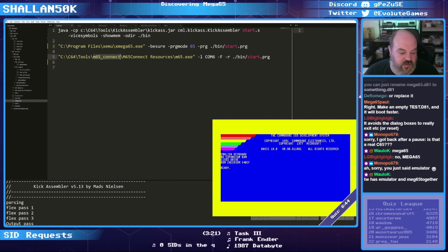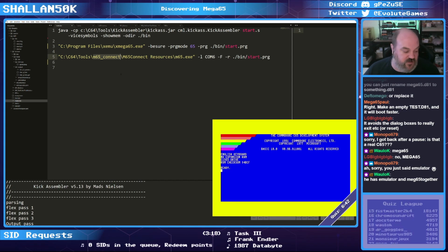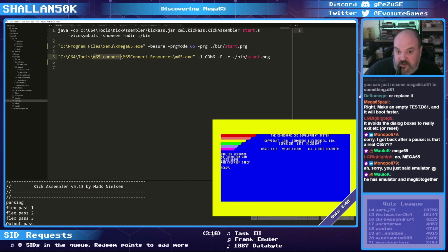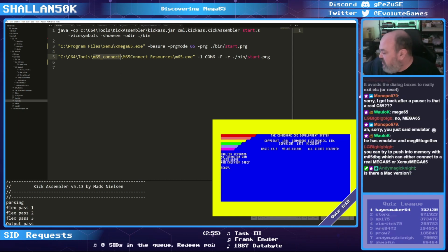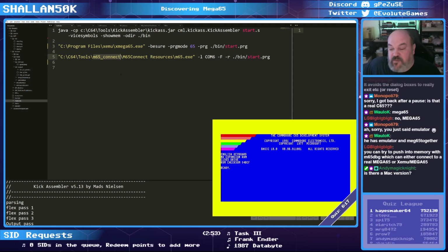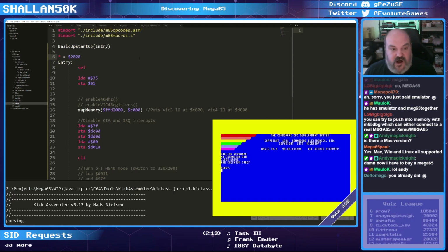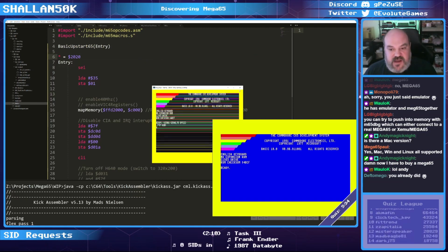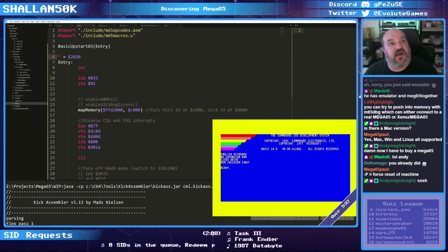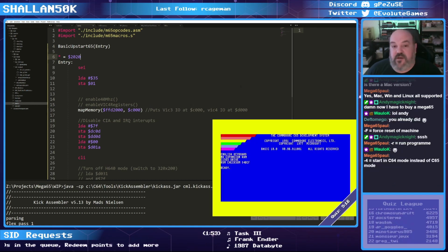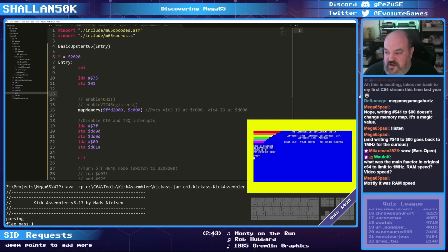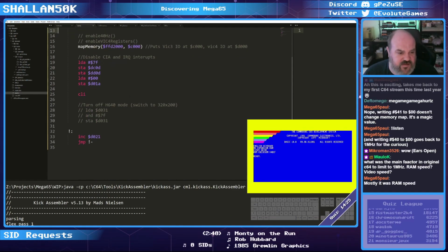Now that is available through the Mega 65 GitHub. What it allows you to do is, through the command line, launch PRGs over the JTAG connector through USB. If I try and load a file, it will do the build and launch the emulator. Then as soon as I quit the emulator, the Mega 65 will kick in and load it on the machine. So the first thing I did was just do some simple tests, really.